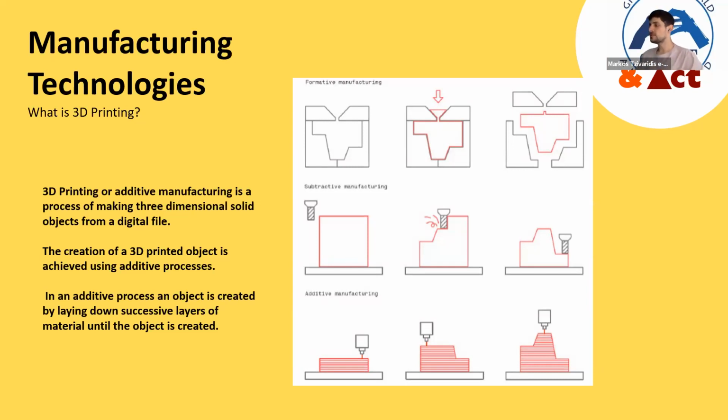The second method is subtractive manufacturing, which is an umbrella term for various controlled machining and material removal processes that start with solid blocks, bars, or rods of plastic, metal, or other materials. They are shaped by removing material through cutting, boring, drilling, and grinding. The disadvantage of this process is that a lot of material is wasted, because you have the cube and you start subtracting and subtracting material, which means that you spend more material than you actually use. And of course, it's not environmentally friendly.